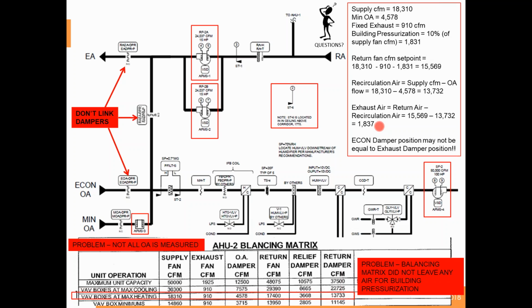I'm going to try to get one more question in, but like I said, there's been several that have come in, so if you're fine with getting these questions after and following up, that would be great. It says, have you had experience with modulating the RA fan speed to maintain a slightly positive RA discharge plenum static? Yes, and that's a good question. They're talking about maintaining a positive pressure over here, so that way you don't draw in air over here.